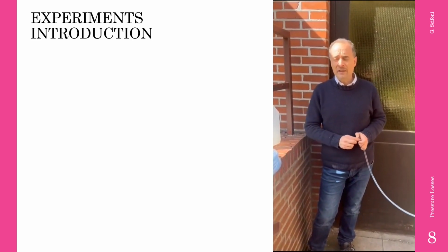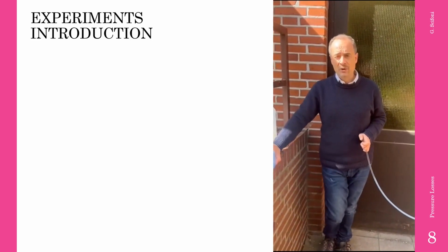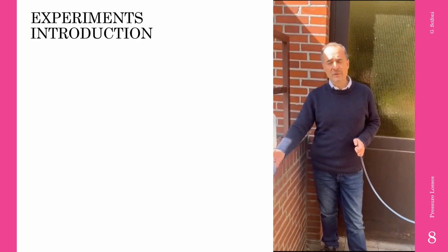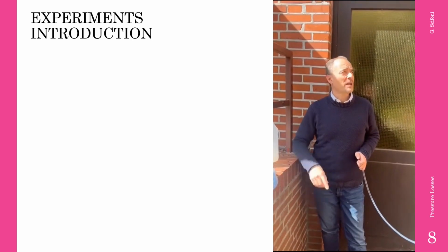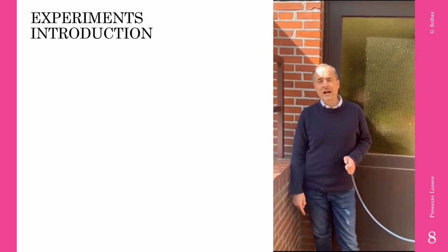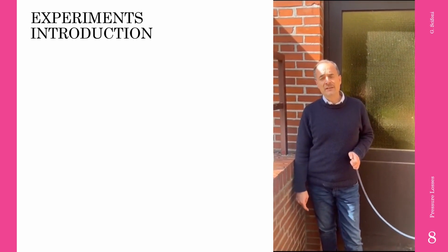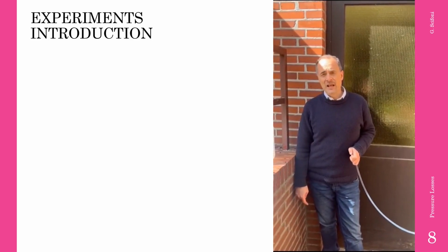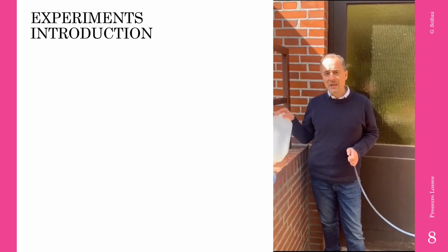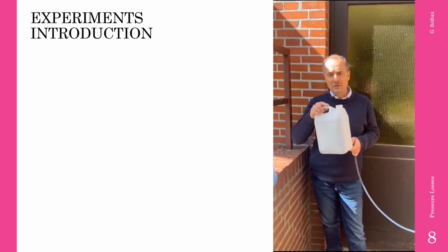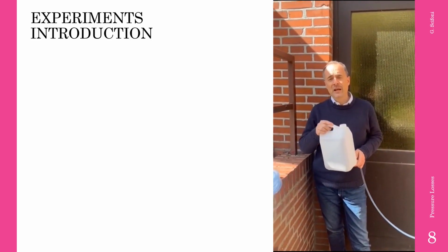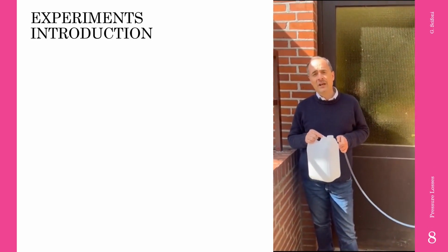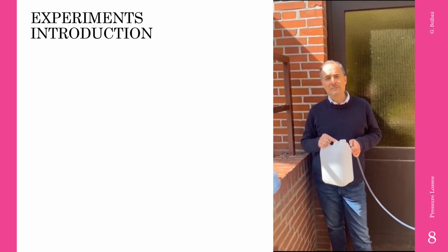The last experiment is using the long pipe, also the 12-meter length, 12 millimeter wide, but with a higher difference in height. Instead of 2.65, 5.5 meters. And in any experiment, we assess the time to fill the canister. And then we'll study what is the effect of the hydraulic resistance case by case.